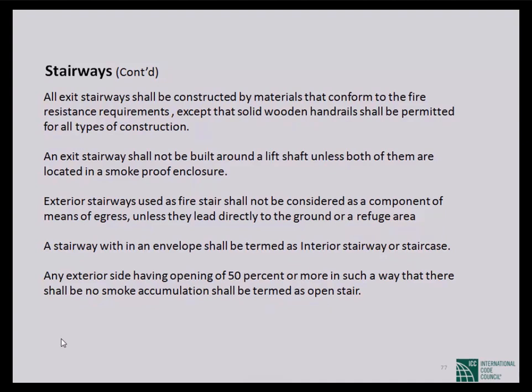Normally the friction factor of tiles, when glazed, is less than 0.3, particularly when wet. So you have to be very careful, because when people are coming down, a sprinkler can come on, or some hidden water can come from anywhere. So there is every chance of a fall. You have to be careful of the slipperiness. But it is not written in the BNBC, it is in the NFPA. Your floor must not be slippery, so that people don't fall down. The friction factor value is 0.5 for non-slippery, or 0.3 is very slippery. So you have to be careful of the slipperiness.